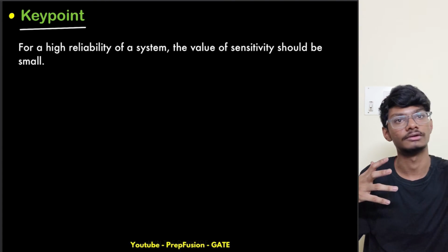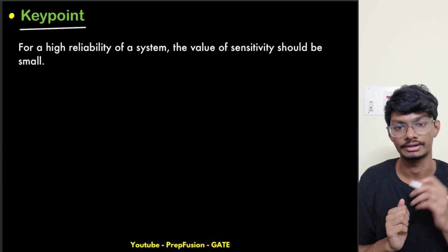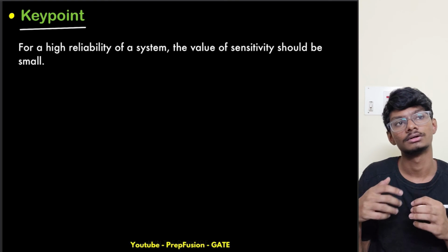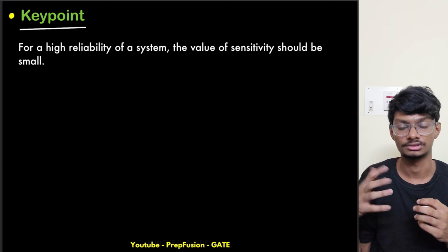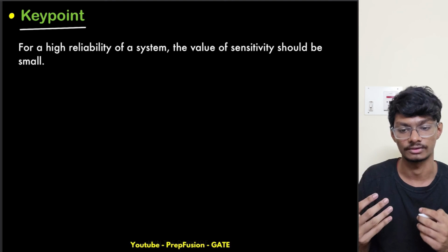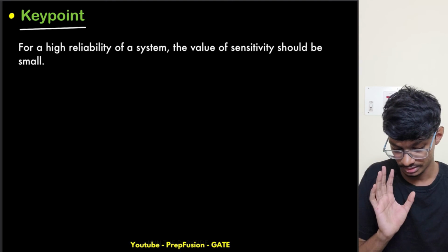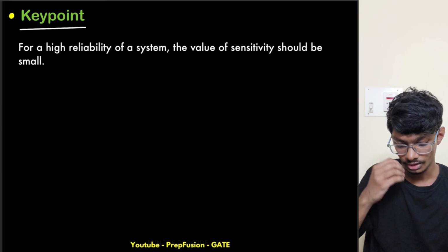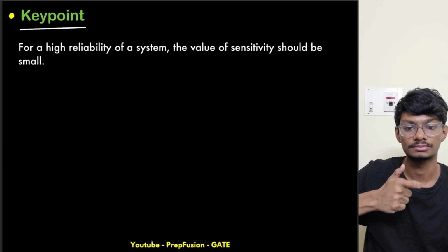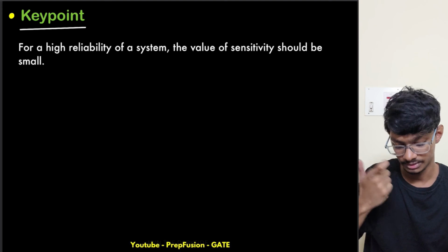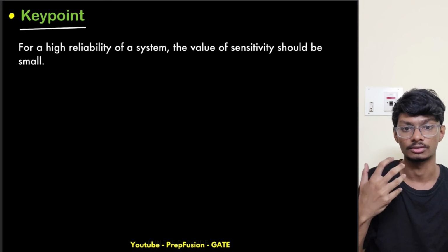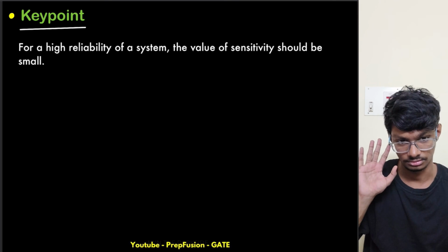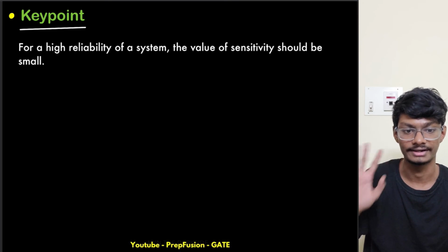Let's say this fan is rotating, but some outside wind comes and the fan changes its speed, then there is an issue. It shouldn't change its value. So this is one thing we need to keep in mind. If our system is much less sensitive, then it is only good for us. That's why we try to make the system as insensitive to small disturbances as possible.